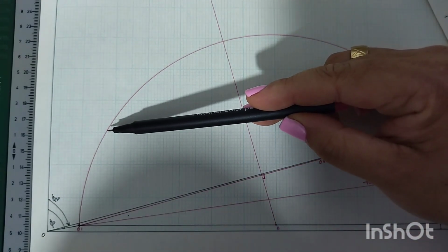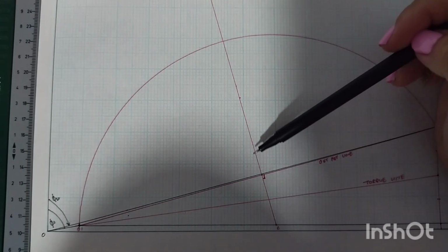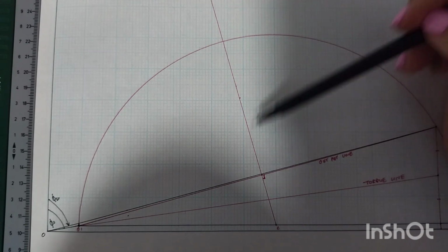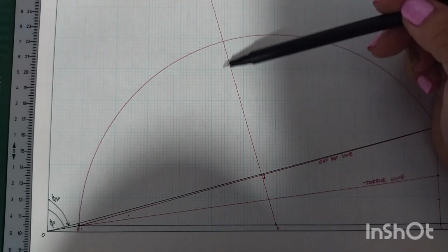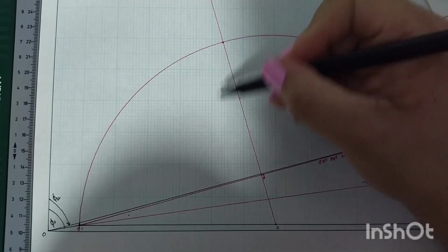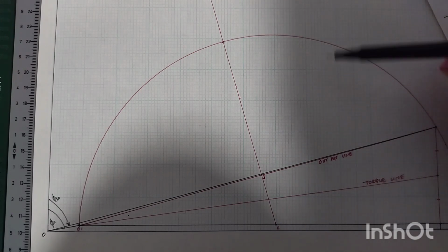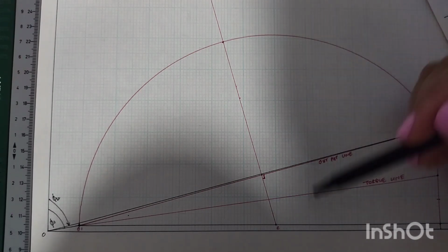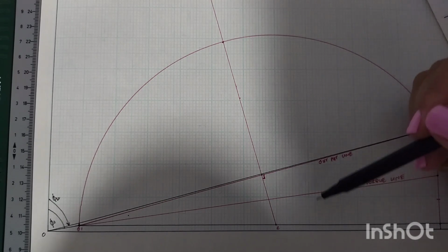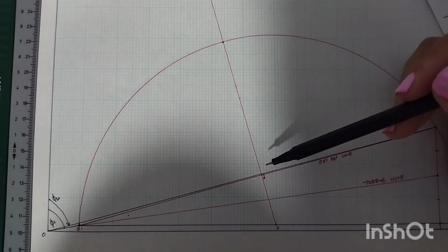The first one, as I'm indicating on the page here, is your full load. For full load, you're going to draw a tangent from O to your semicircle. Remember that line that I'm pointing out is your perpendicular bisector of your output line. So if you draw a line perpendicular to your horizontal axis, which intersects your perpendicular bisector of your output line, you will get the maximum output. And then for the last condition, which is max torque, I will show you how you will determine that.